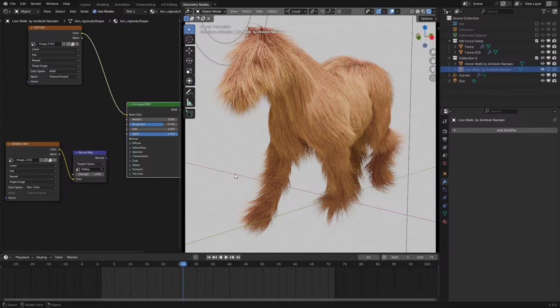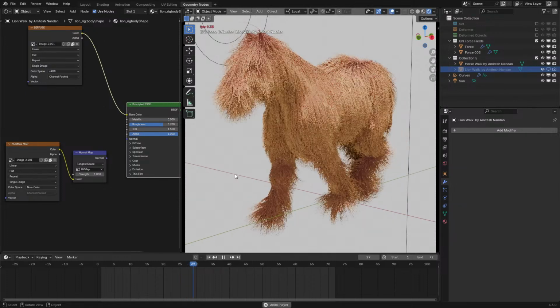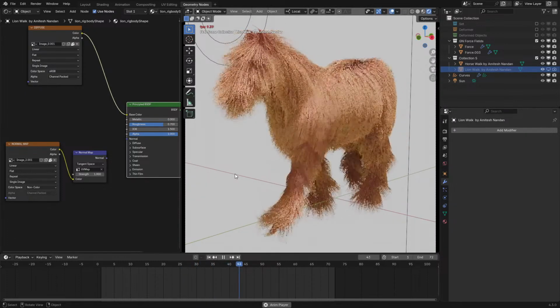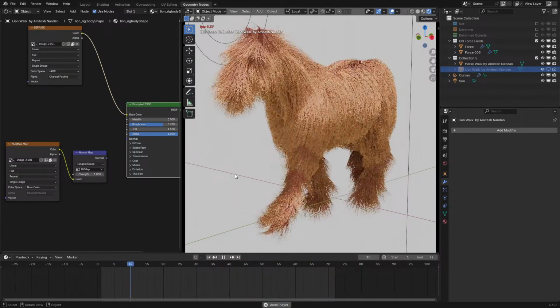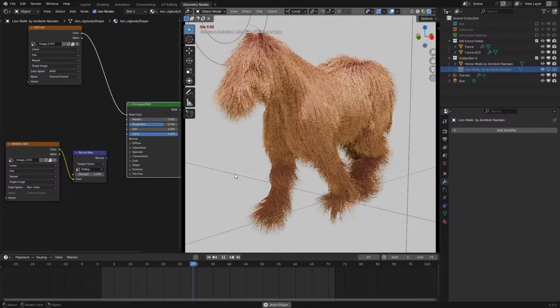Then also with curve length stiffness, that's also very slow with geometry nodes because you have to use the repeat zone, and the repeat zone plus the evaluate at index zone just really don't mesh well. They get very slow very fast. So in this case, I'm just using the accumulate field node to fake the length constraint. I mean, it does work, but it's not super accurate.